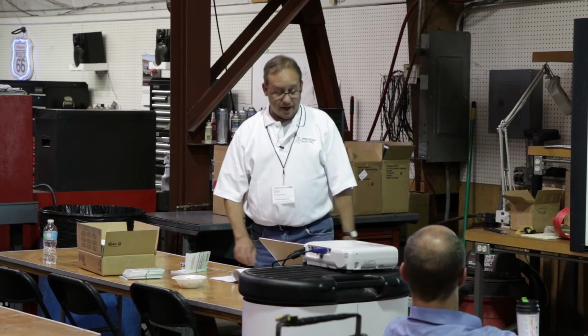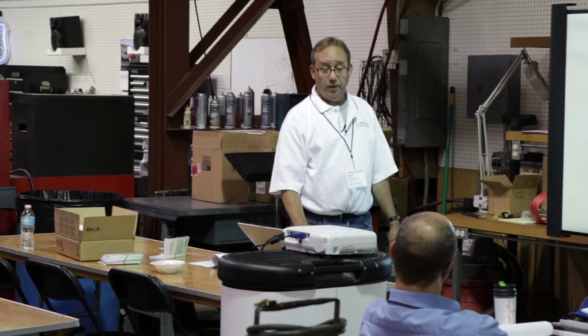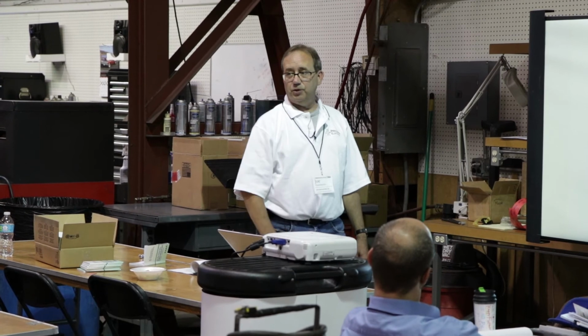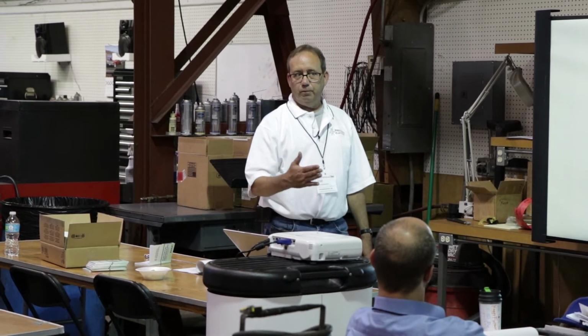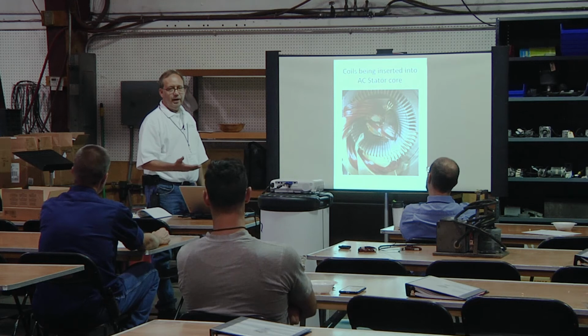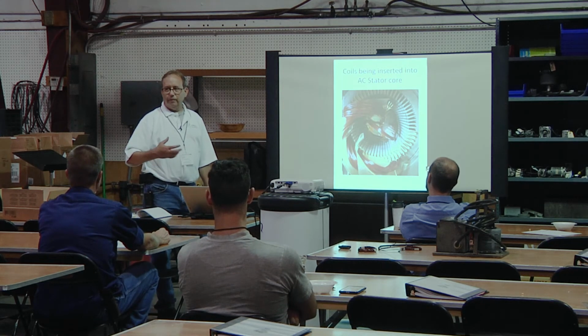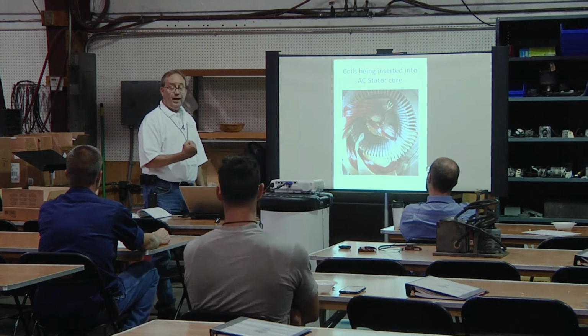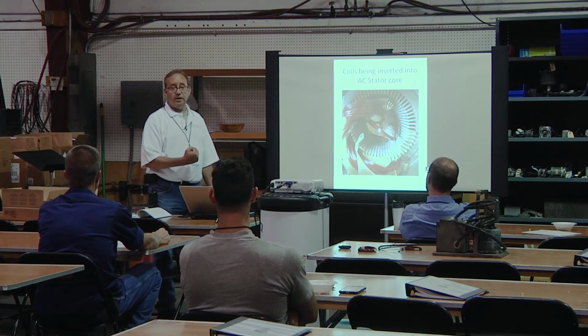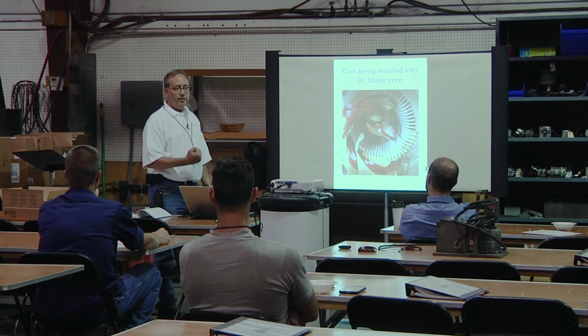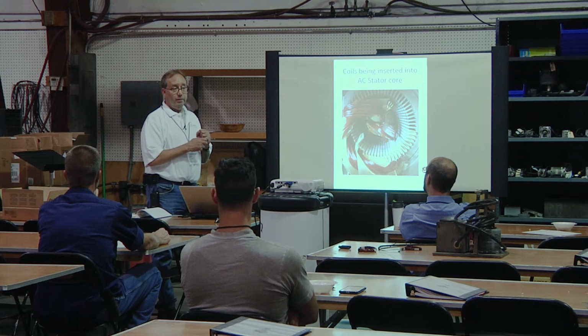Apparently that was because they lost feedback and their drive didn't fault out or trip or anything. The mill just took off. It broke out. What had happened is, in a mill like that, if the load breaks out, then you've got that motor under a lot of power. I mean, about 1600 amps. And if they got that thing running at, say, 400 or 500 foot a minute, that motor's cooking along. It's probably going 1,200 RPM. And you've got an armature that's probably that big in diameter, so it's a lot of inertia. Physics is just taking over.